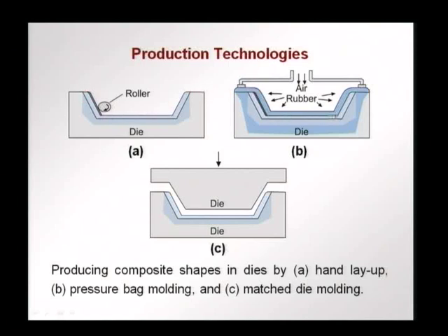This light blue here is the final FRP composite. So, if you have a surface that is not just flat and that has to be reinforced, then you would have to make a die like this, and this will end up giving you a FRP composite of this shape and sufficient stiffness now to be adhered to the surface that we have to strengthen or reinforce.